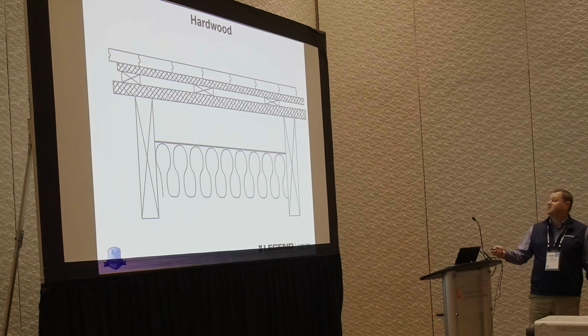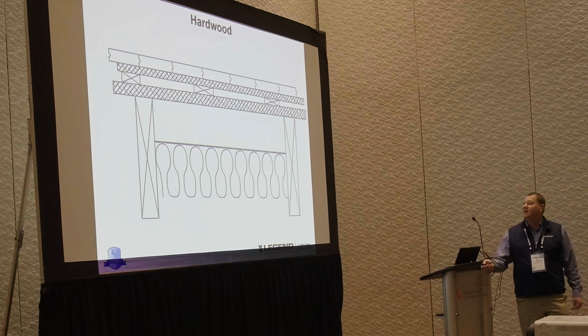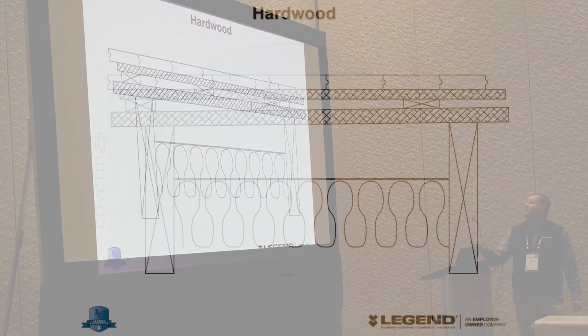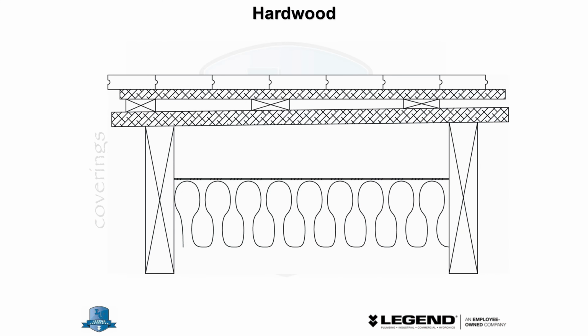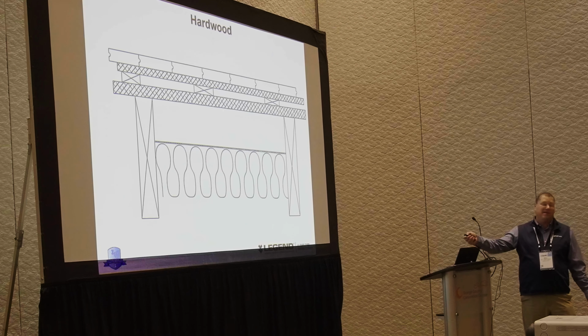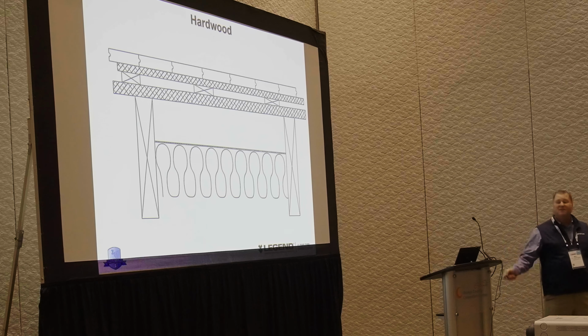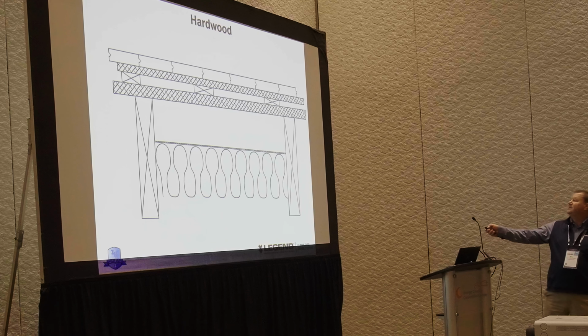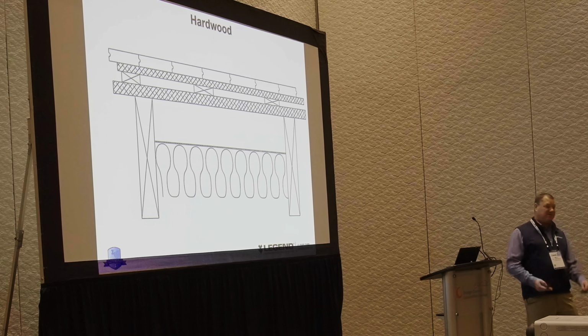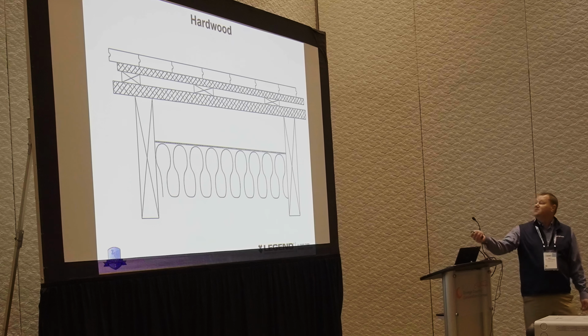Making sure you know the construction, especially if it's a retrofit. You know, this is a typical, maybe a 2x10 and a subfloor here. We did a project one time where they ended up putting sleepers in and putting another subfloor above that. Don't know why, but they did. And then they were putting hardwood on that, and we were going to try to heat with heat transfer plates from below. We didn't know this existed. Luckily, I think the contractor was doing something near the stairs, and he was like, whoa, what's that? And we started looking at it.